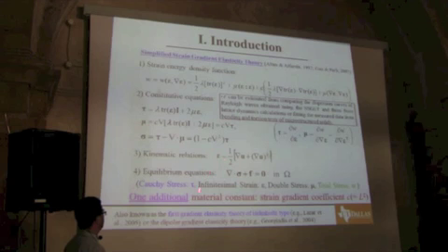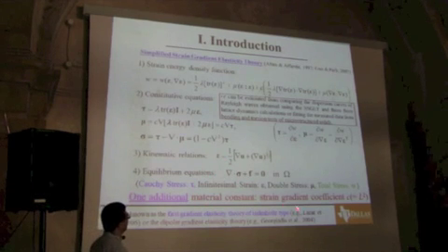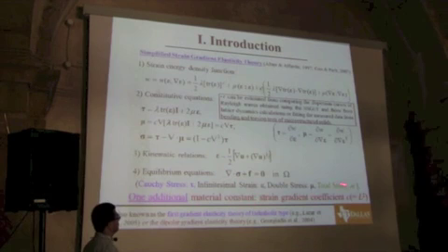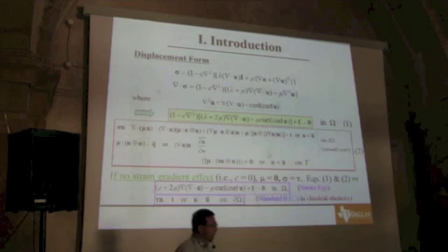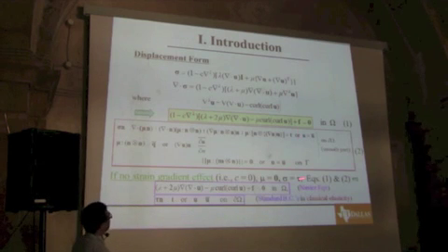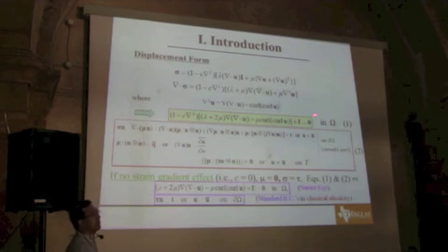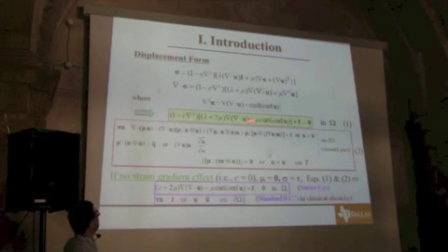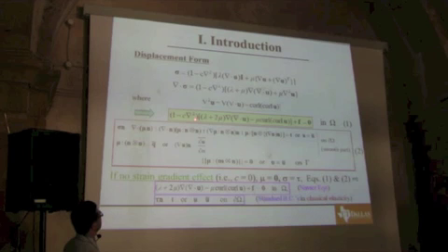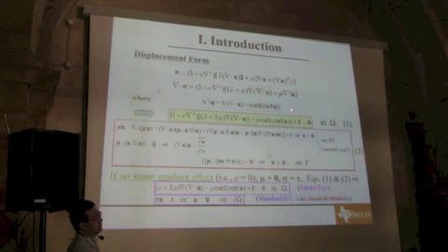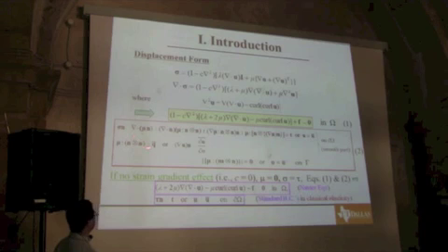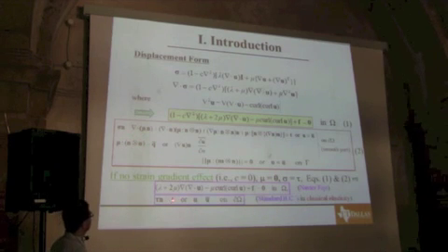I think this now gives us some good freedom to deal with the microstructure dependence. So the complicated part is the boundary conditions. The governing equation is more challenging than the original Navier type equation because of the involvement of this higher order term, but it's more manageable than the boundary conditions. If you look at the boundary conditions compared to the classical ones, they are just much more complicated.